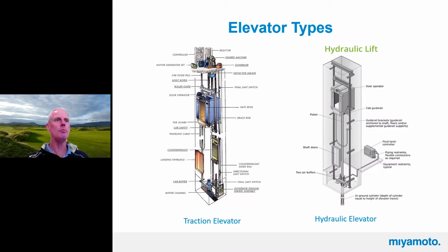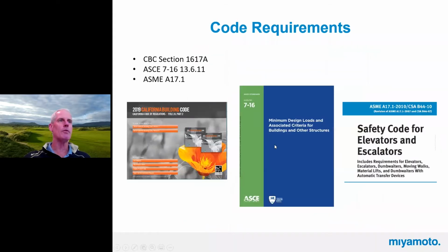The elevator guys pick up, you'll see these little brackets going along so often. And typically we'll space those 4 to 6 feet up our guide rail supports. So they don't really run floor to floor, although they could use a heavier rail and span floor to floor. The elevator guys typically don't. Apparently it doesn't work so well for them. So that's how that works. We will be responsible for the guide rail supports.